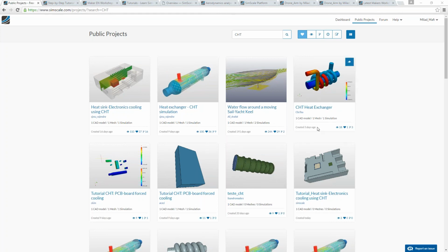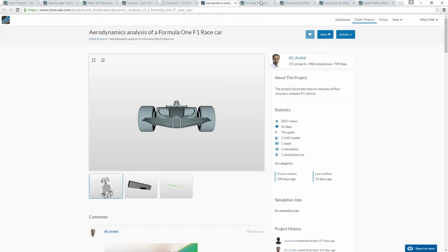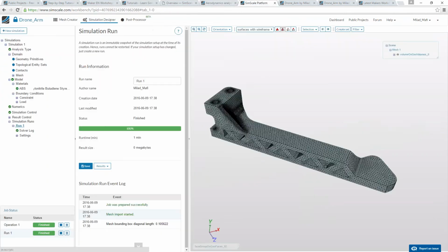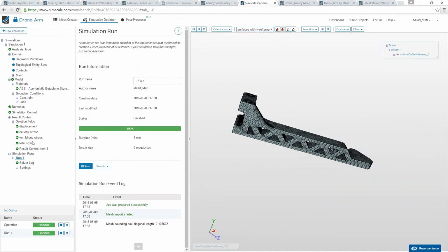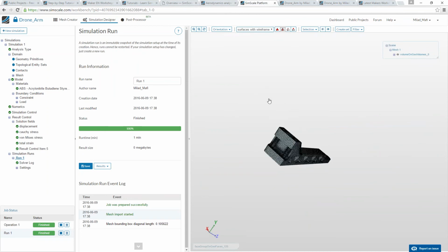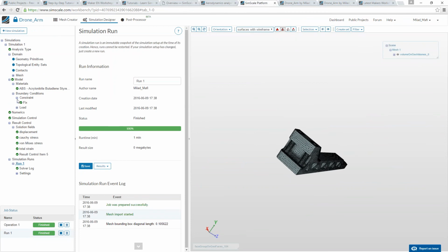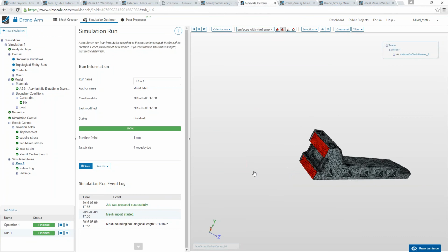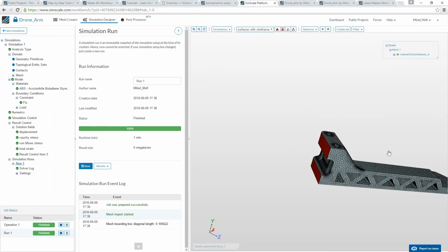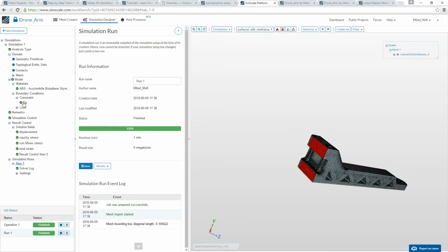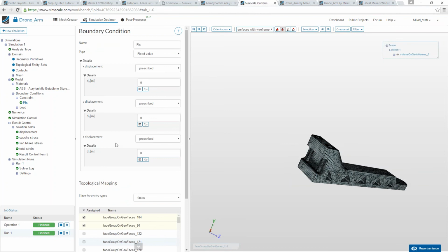Okay, boundary conditions. Well, for example, maybe let's go back to the simulation itself. In the end, I can only give boundary conditions to those areas where I know what will happen. I know that this and this face cannot move because I'm looking at the relative, let's say, it should be fixed here, so it cannot move. And therefore, X displacement, Y displacement, Z displacement can be prescribed with 0.